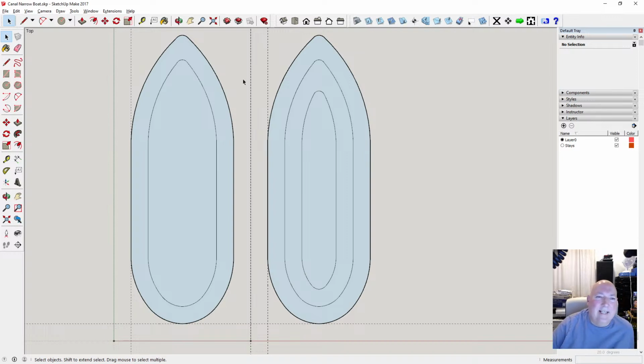and we don't want to go to the extent of milling both faces beforehand. It's not going to be that exacting, and we're going to sand it down as well with the electric sander, just to make the surfaces smooth on the outside, not the inside. They're going to be as they are. I won't be trying to sand any of this down, but this will be good enough to be left as it is. It's just the top surfaces, the other sides that aren't going to be milled, they'll just be sanded down. So I need to keep from the 20mm, I need to work out what the percentage is.